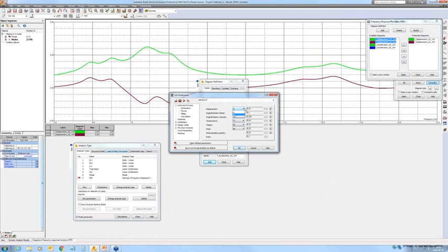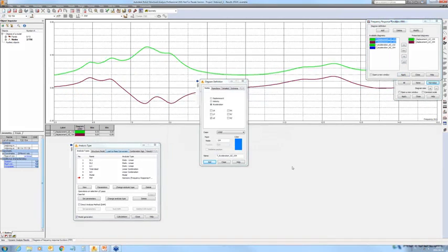I will go again to units and I will change the units to millimeters. Okay, yep. So that was, if I remember correctly, 0.24 millimeter. Now we have half of that value. So you can see to which degree damping influences the obtained results. Okay, let me go back to the presentation.